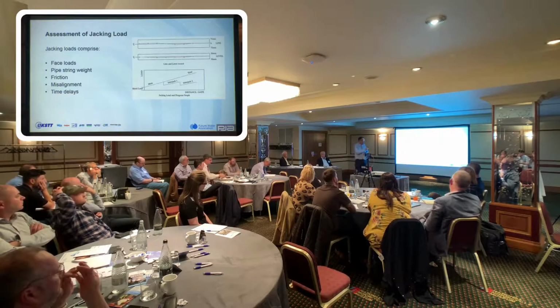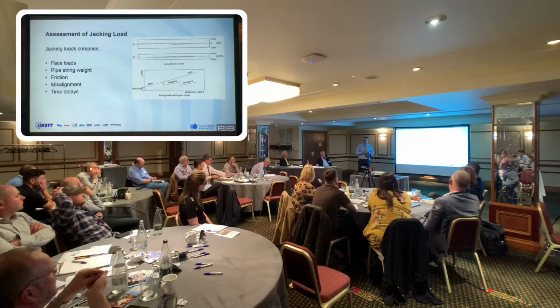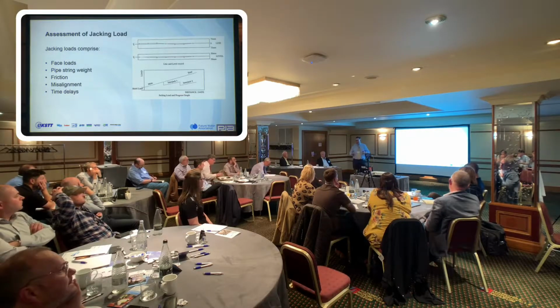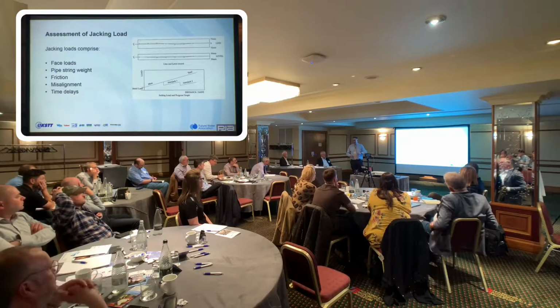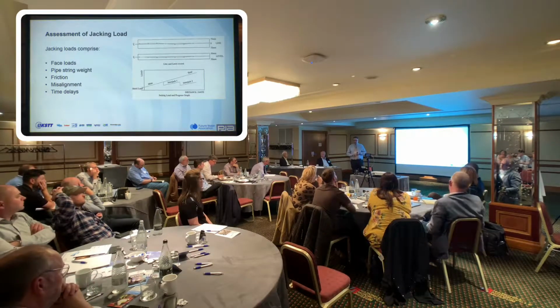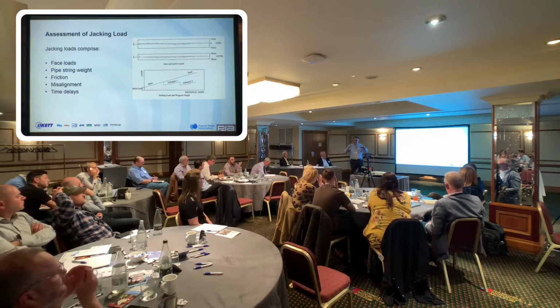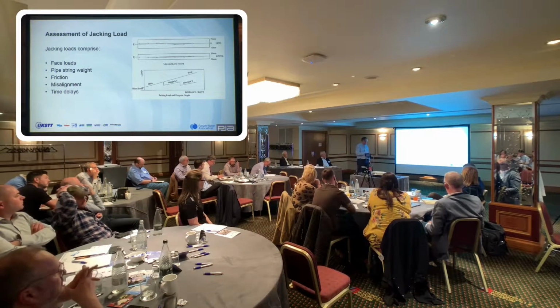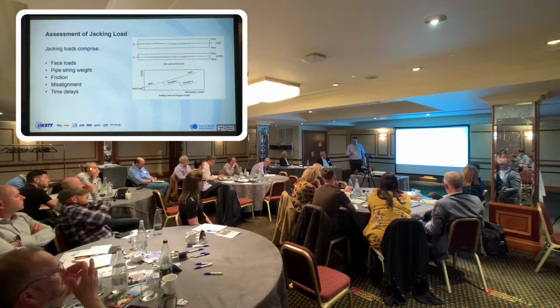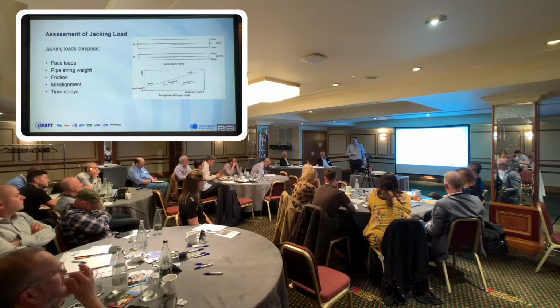But if you stop, obviously all the good things that can happen, for example, they can close the valves and make sure that they've got the lubricant trapped in the annulus and try and keep the pressure up there. But obviously if you're delayed for any amount of time and you start getting lost there, then that ground wants to come in. So if the ground comes in and ultimately grabs hold of the pipe, then that increases the friction load. And very often, I think the startup loads can be quite considerable to get going